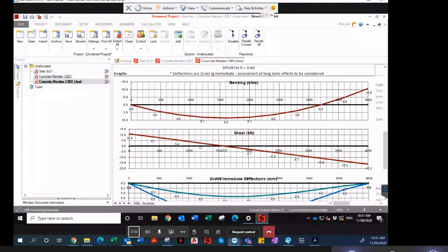And in a similar way, you will see something similar happening to your two-way slab too. The two-way slab is more forgiving because there's more distribution. It distributes it in both directions. That's the reason why in a normal raft slab, I'm not worried about the negative reinforcement or the negative moment.